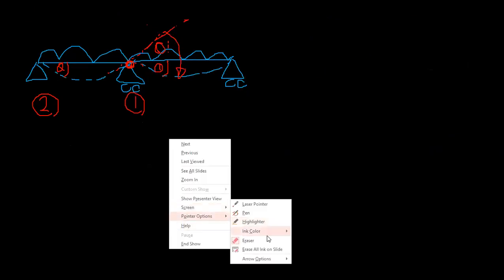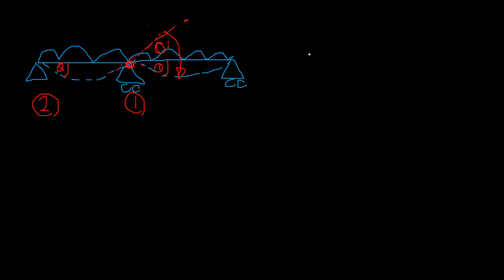So the flexibility, don't forget that, right? So here you need the actions and the forces, displacement. So the displacement D1, how much? 2 theta. D2, theta. Okay, so we can find the displacements from the appendix, right?